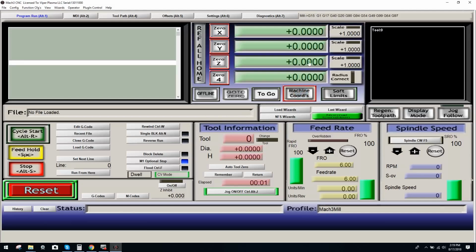Once you click this button once again, you're validating that you're at your end stop position, because once again, the measurement that you're receiving from this on all your DROs will be the measurement to your end stops. Click it again. Now we're back in G54.